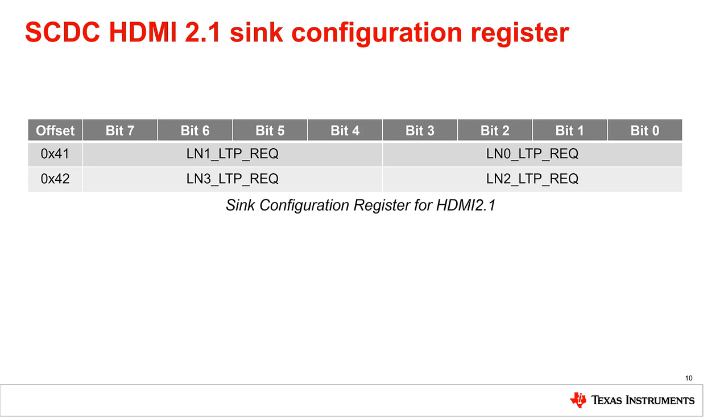The last two SCDC registers we will look at are registers 41 and 42. These 4-bit fields correspond to each HDMI lane. The sync sets these registers to indicate specific data patterns for link training, specific data patterns for compliance testing, request the video source to increase its FFE level if it is supported, and to change the FRL data rate.